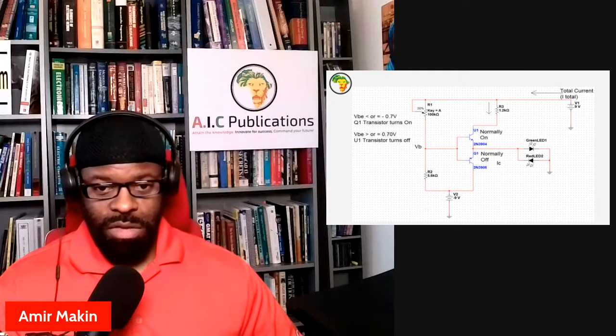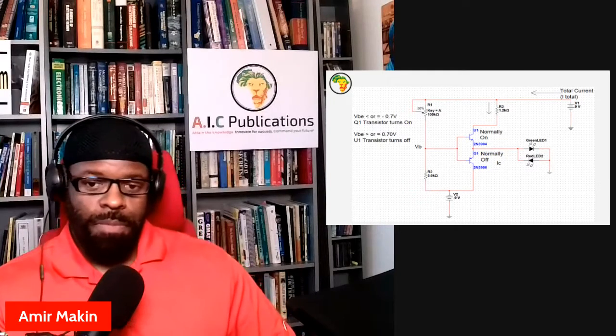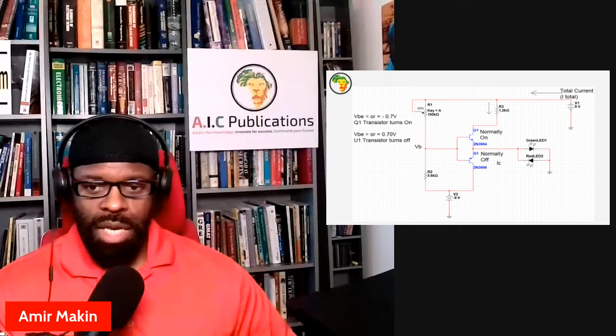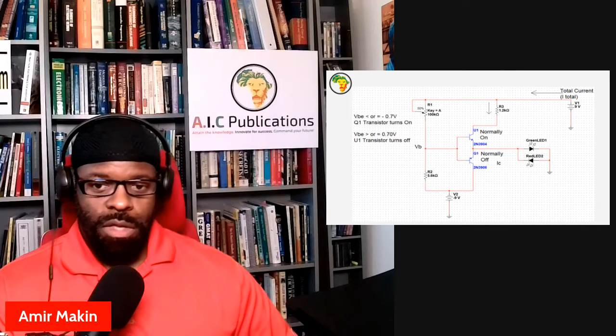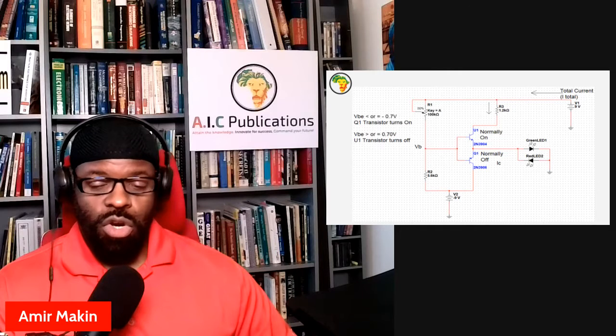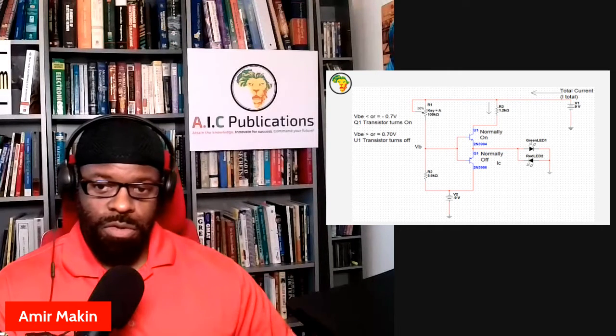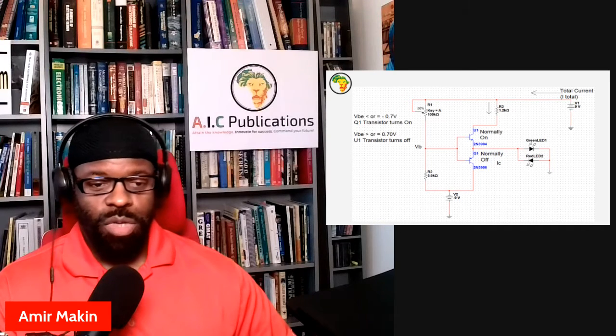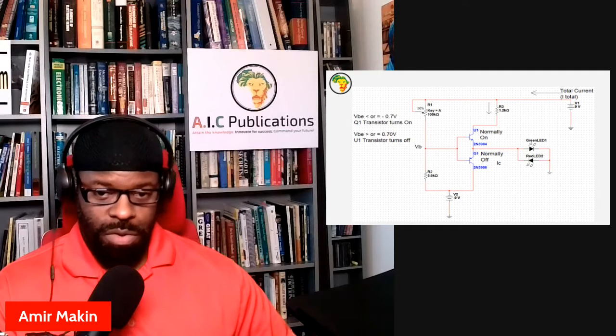Let's go over the circuit that we've created and designed. Okay. The first block that we just talked about is the power source. And this is going to actually be the positive rail power source. Now, the way that electric current flows, it flows from positive charge all the way to the negative charge or the ground. That is the way that conventional, normal, positively charged current flows. And with an NPN transistor, that is the normal way of flowing.